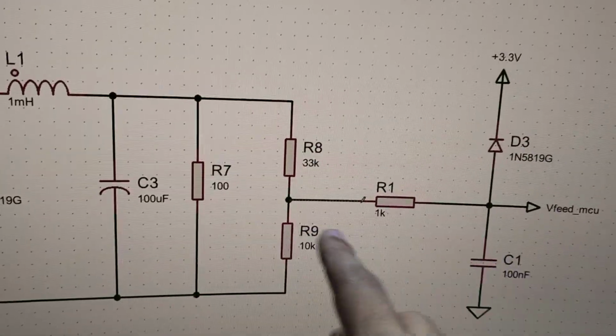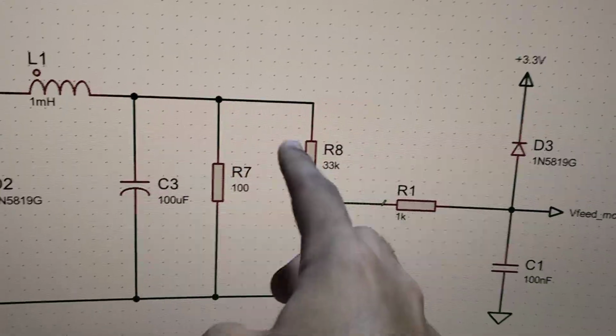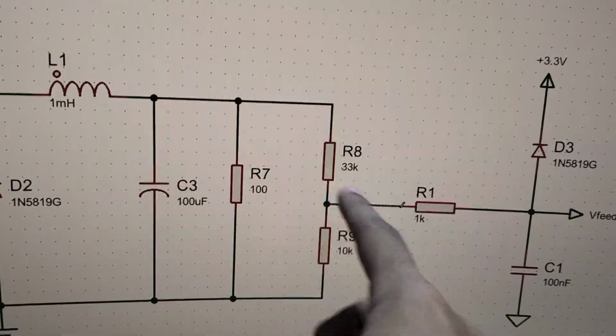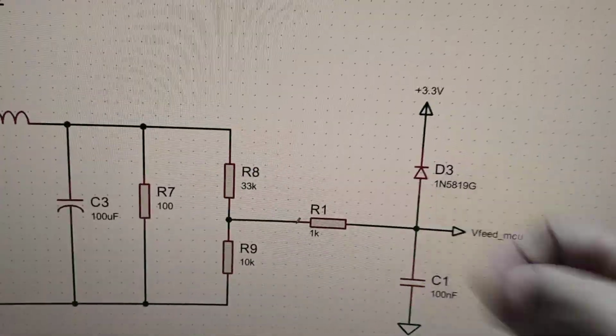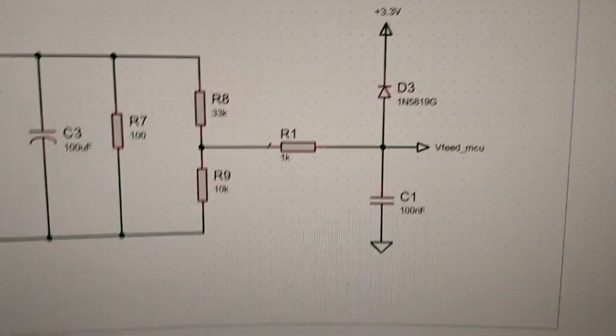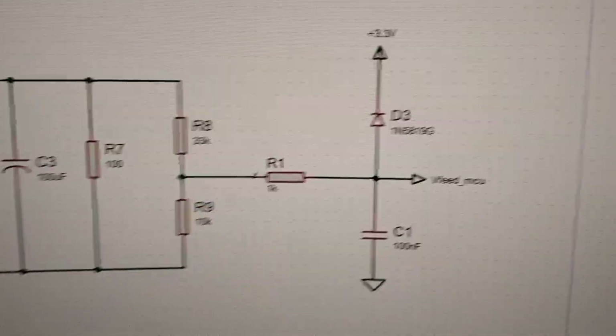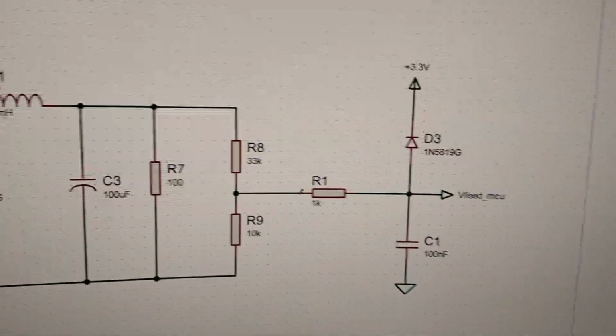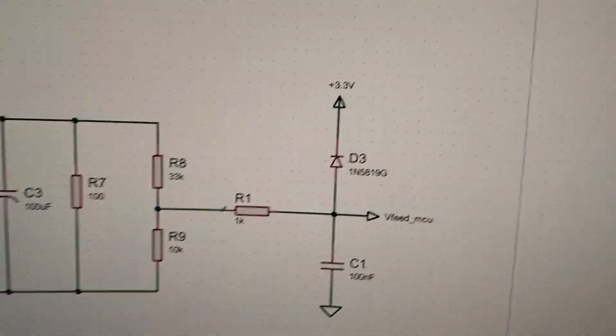Over current protection is there because you have this resistor divider and the current is already low, and over voltage is there because you have this clamping diode. So both of these important things need to be handled generally when you are combining power electronics with control. On a microcontroller you need to have these two protections.